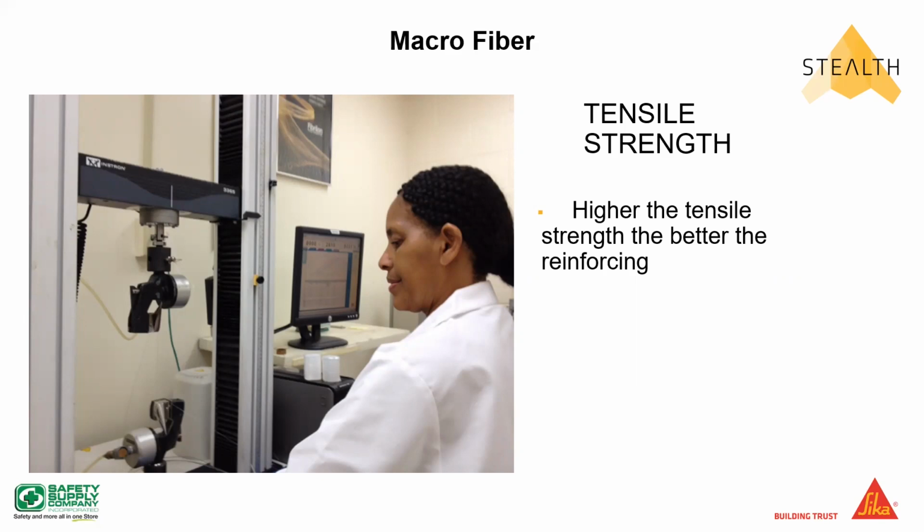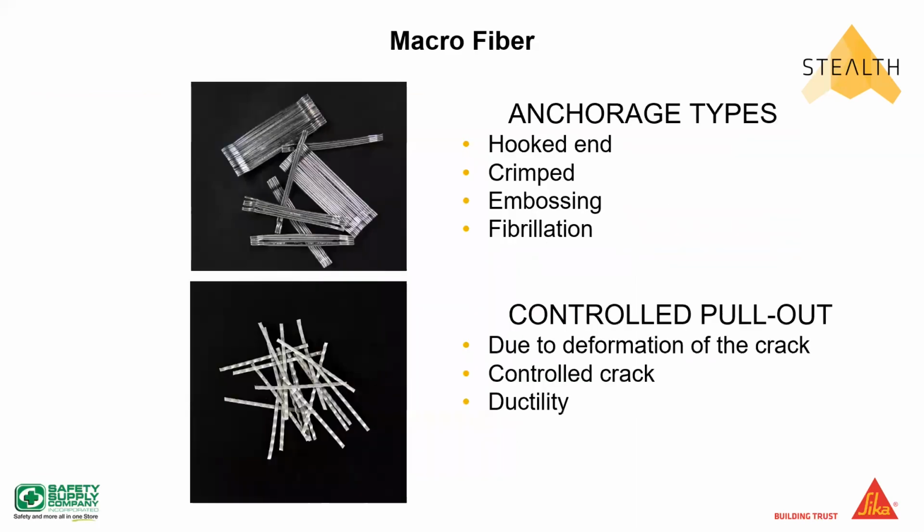All the attendees think I'm setting them up, and they say, oh, the macro synthetic fiber, and that's not the case. A single steel fiber is much stronger than a single synthetic fiber. But where the difference is made is in the number of fibers you get in a pound of macro synthetic versus a pound of steel fiber. There's much more fiber in a pound of macro synthetic fiber than in a pound of steel fiber. So just a neat little note I like to toss out there.